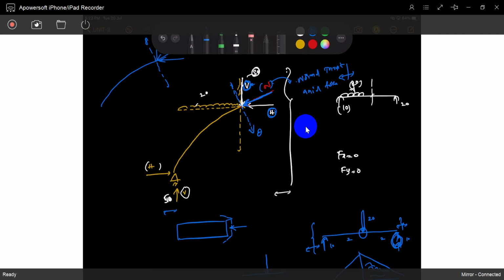Just observe it. The loads are distributed throughout the span. You applied a 20, but throughout the span experiences some forces. The forces are in terms of shear force, moment, something like this. So that is the distribution of the loads. Understood? Distribution of the effect. The load effect is distributed throughout the span. In the linear spans, the load effect is distributed throughout the span by moments and shear forces. But in the arches, the force experienced is distributed throughout the span not only by moments, but by some axial force.